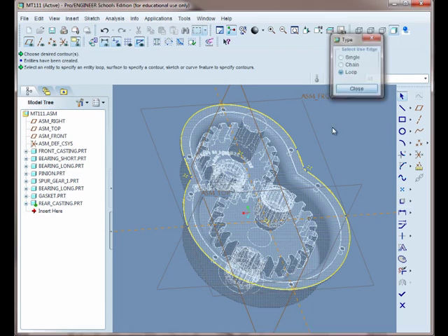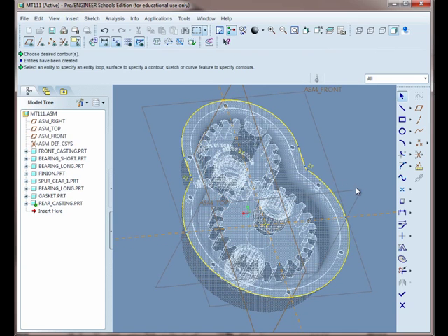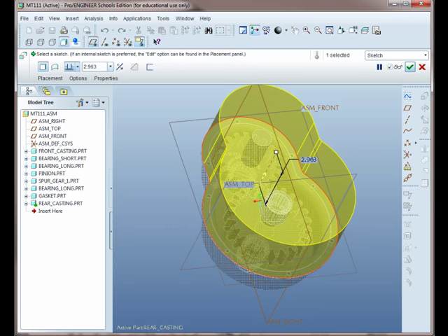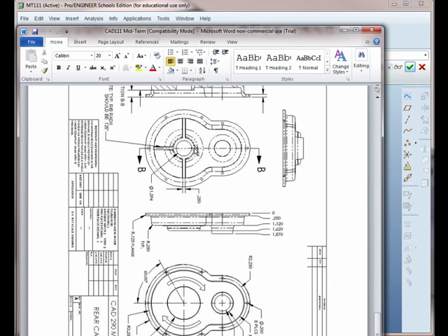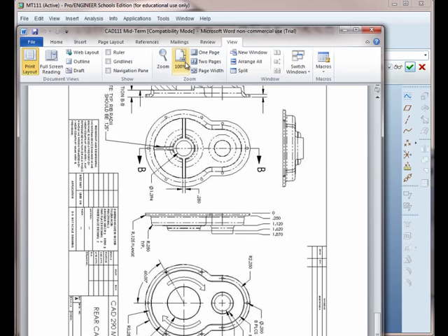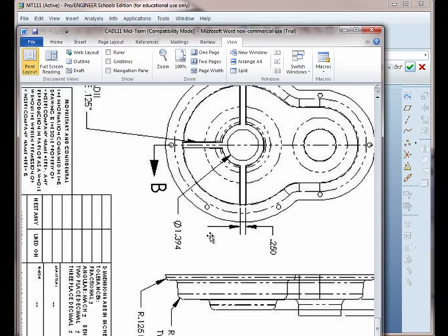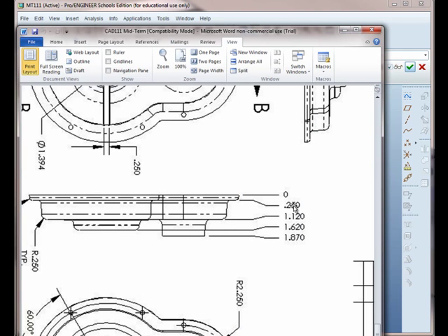Okay. Now be careful not to actually try and put those features or the holes in here yet. Right now this is just going to be a solid extrude, and then we'll shell it out when we're ready. So here I'm going to hit Done, and I could go to Extrude, and then if we look at the drawing, and I'll zoom up here, the drawing indicates that the thickness of this flange is 1/4 of an inch.